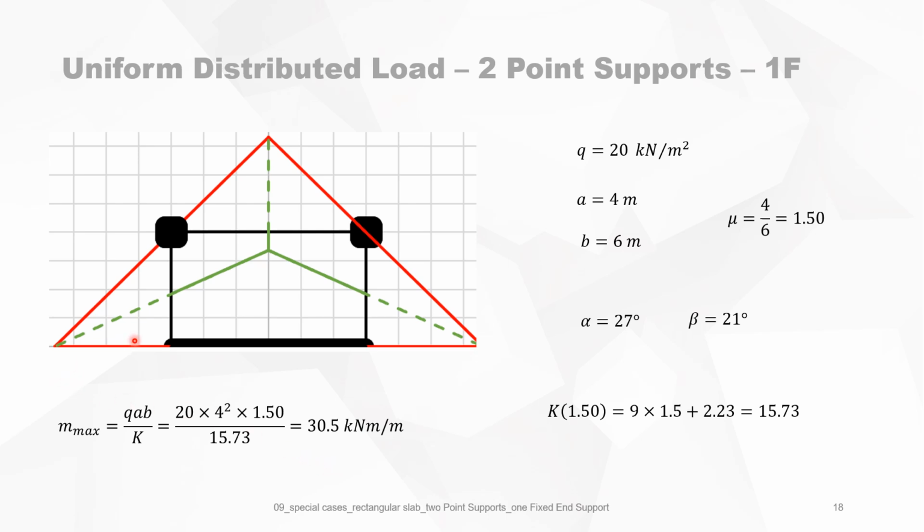When you compare this with video 8, which is about this being simply supported, then you see that when this is fixed, A1 increases. So this portion of the yield lines gets bigger, which is normal because the fixed end support attracts more weight on this side.